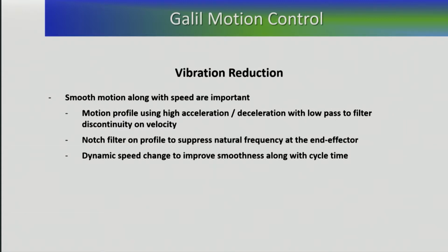on the profile. One of the other options is to understand conditions that result in the resonances. In those instances, you could say, when I go around a certain path at a certain position, you start seeing the vibration and it dies out. So if it is a specific region in which you see the vibrations, one of the other ways is to define your motion so that, from segment to segment, you dynamically change the speed and use the accel and decel, transition to lower speeds where you're less likely to excite the resonance, and then bring the speed back up as you clear that area.